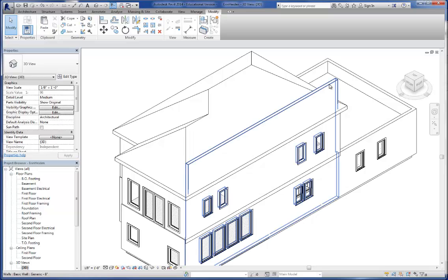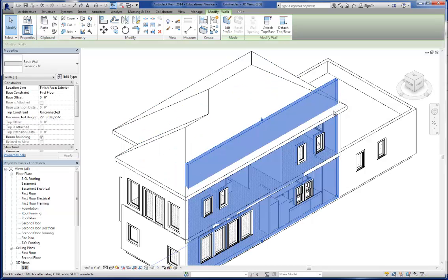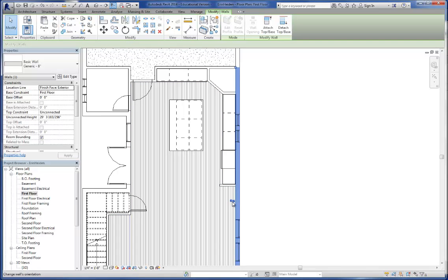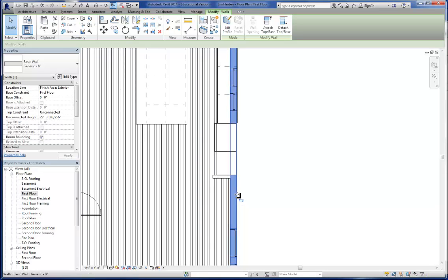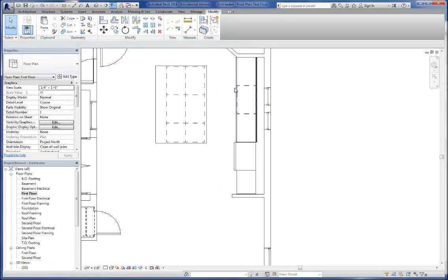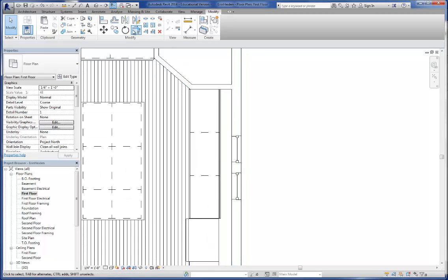So now this is an important thing we need to do before we start adjusting the stack walls. We need to make sure first that everything's oriented properly here. I've gone ahead and done a quick check, and her wall is actually, the exterior face is facing inward, so we want to invert that relationship, and you can see that's going to have an impact here on some of the other stuff that she's actually set up. So we'll go ahead and take this, and I'm just going to pull that out. And so now, assuming that this was all aligned properly, we can use the Align tool. And instead of center line, we'll do this to wall faces.